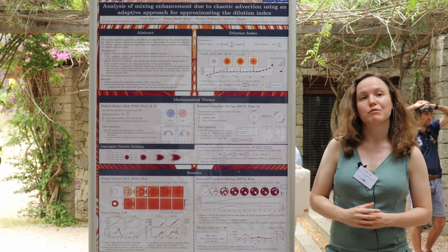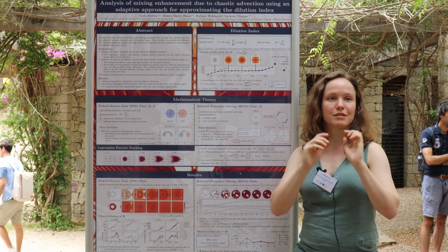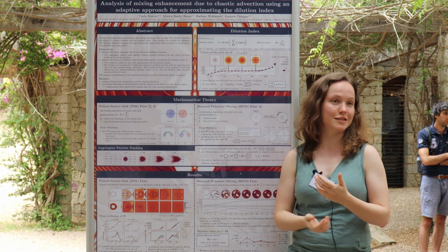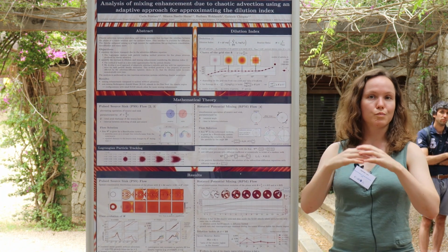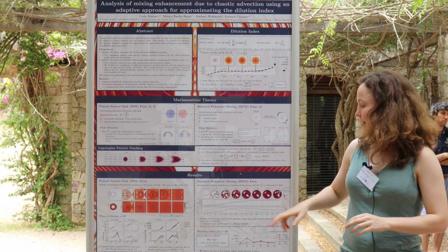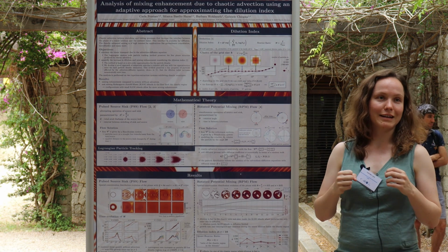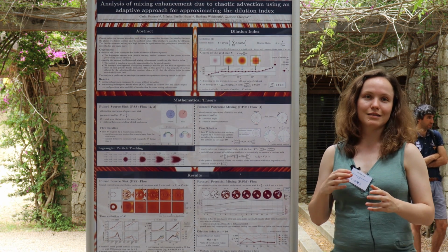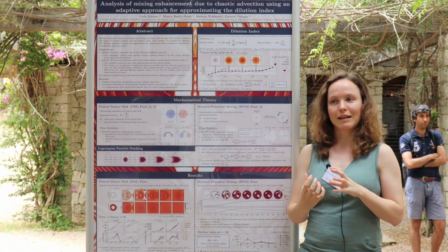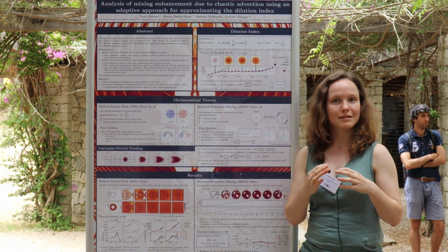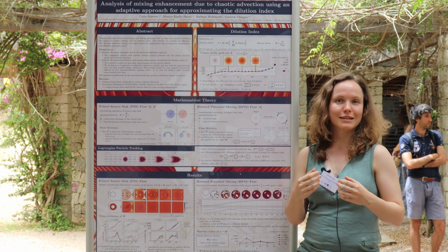Going over to the rotated potential mixing flow, we have the same initial setup. We place the particles close to the source at the beginning and then we just start the system. What we find here is that we spread the particles pretty fast in a big area of the system. This area where we can spread fast is called the chaotic area, while the rest, where we find fewer particles, are the calm islands. This is a specific feature of the flow field and they reduce mixing. By analyzing the size of these non-mixing calm islands, we can predict beforehand, before we have the simulation, if the mixing can be very good.